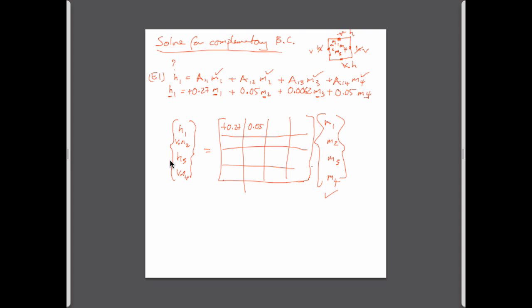That's it. So step back. It's been a lot of kind of juggling things around, but basically the idea is you have a fundamental solution that satisfies your governing differential equations, satisfies continuity for flow, and it satisfies Darcy's law substituted into continuity. It satisfies that on its own, and by superposition, if you have a whole bunch of them, it still satisfies that behavior. You can show that it's so by substituting it into the governing PDEs.